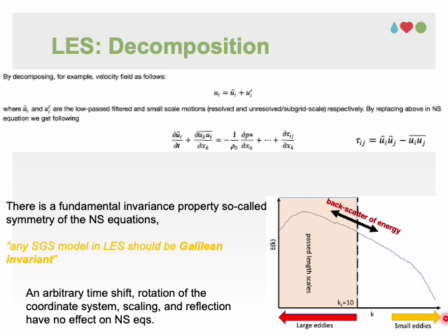However, at subgrid scale, the energy transfer occurs through a process called backscatter, in which the energy is returned from small scale eddies to large scale eddies. This process can affect the accuracy of the simulated flow field, particularly when the flow is strongly nonlinear or when the grid resolution is relatively coarse.